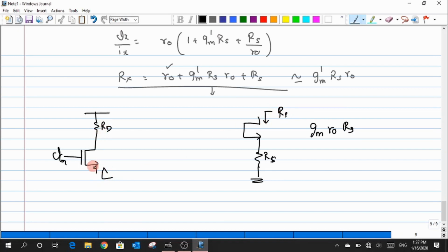But right now I have swapped both these conditions. I have placed my drain resistance and I'm looking through the source. Now what could possibly happen in this case? A simple guess, a wild guess. Here it was magnified. What could happen here? Diminish. Okay, so an approximate output expression for this is that RD would be reduced by this quantity. But again, it is not exactly the intrinsic gain. It is gm prime, where gm plus gmb has to be included in both cases. With this I will stop, and the proof of this I will do in the next class.